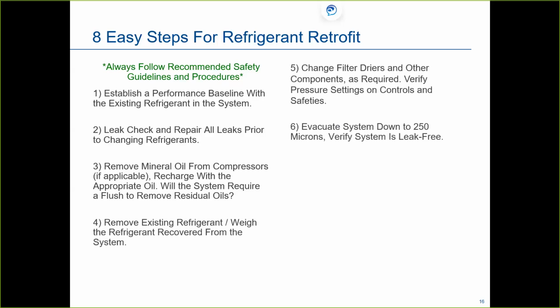I know a lot of guys and gals are going down a lot lower than we used to. Emerson wants at least 500 microns or less. I know from traveling around the nation in the last few years, I see more and more they're going down to 300, 200. It's amazing.